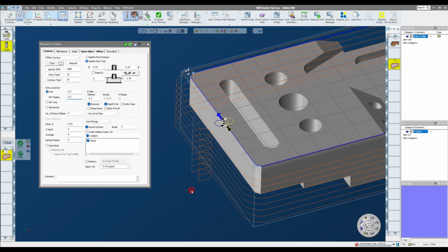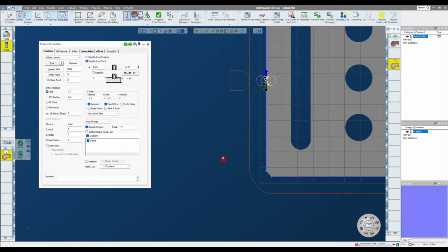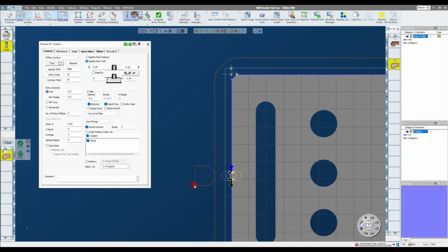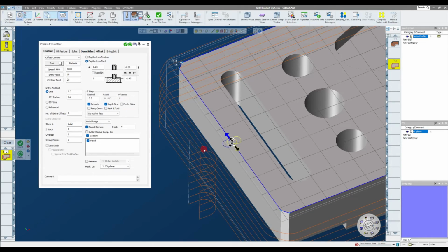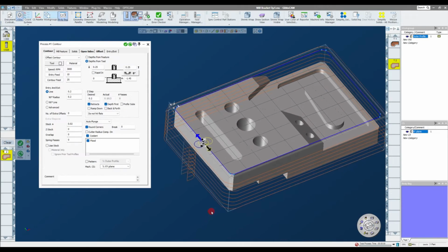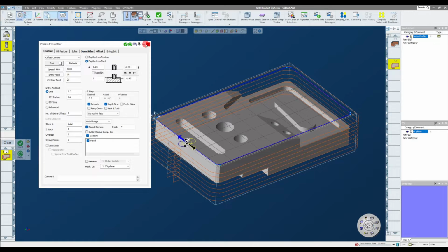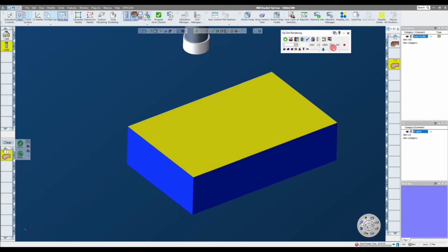Redo that. Now I can see, going to my top view, the tool will come down here, approach 200 thousandths, put a 200 thou radius, and then profile around my part. And when it comes around the other side, it'll do a 200 thou radius and out, and then a 200 thou straight line. And then it will come up and over and down to the next successive depth of cut. If I render this, it looks kind of like this.